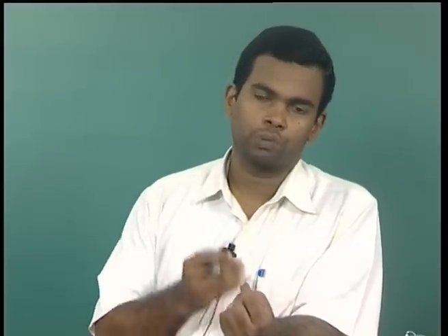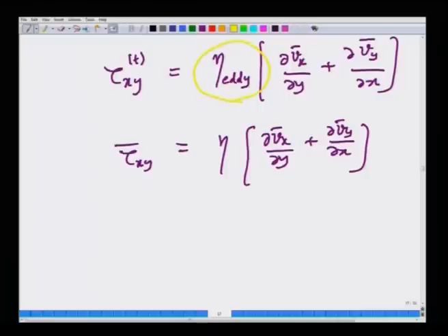So, clearly the eddy viscosity cannot be a constant, it has to be a function of position in order to correctly describe the physics of fluid turbulence. Okay. So, essentially we cannot say that the eddy viscosity is a constant, because otherwise it becomes a trivial problem. So, we have to bring in spatial dependence of the eddy viscosity on the various spatial coordinates. And we are saying that all of turbulence can be described by just one function. Essentially it is a function of spatial positions, but that is certainly questionable unless it is backed up by experiments.